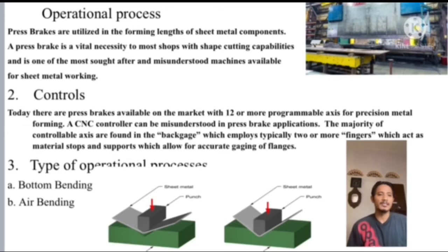The disadvantage of air bending is that the angle accuracy is greatly affected by the material thickness. If the thickness is small, there will probably be a problem, and the ram depth will have to be adjusted as the material thickness changes from millimeter to millimeter of sheet stock.